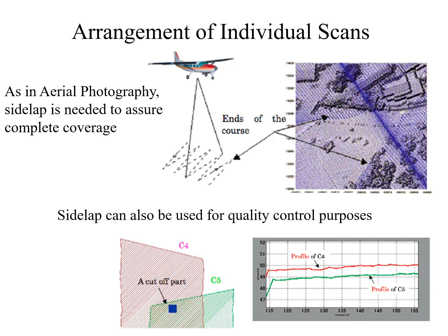And that can be very useful. For instance, for quality control purposes, you have a red colored pass and a green colored pass, and if you compare your results for each one, in this case there's a 1 centimeter difference between what the elevations are in one pass and the next pass, and you can use that information to correct that data.